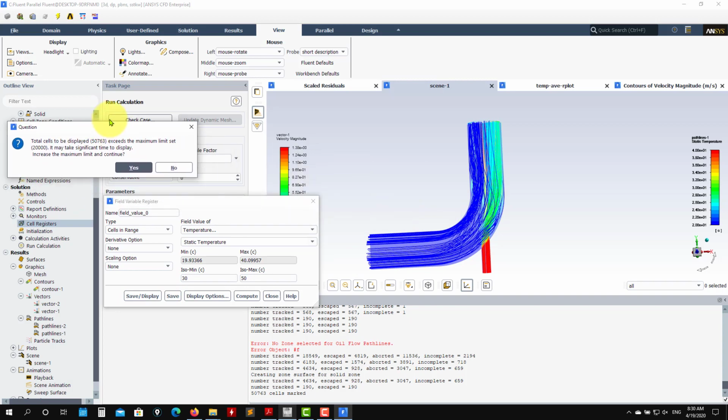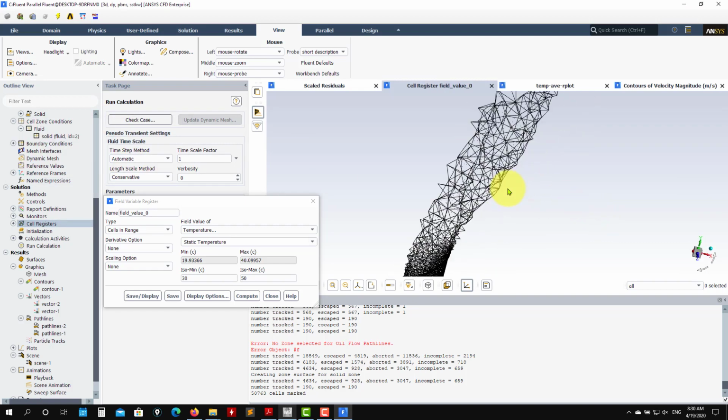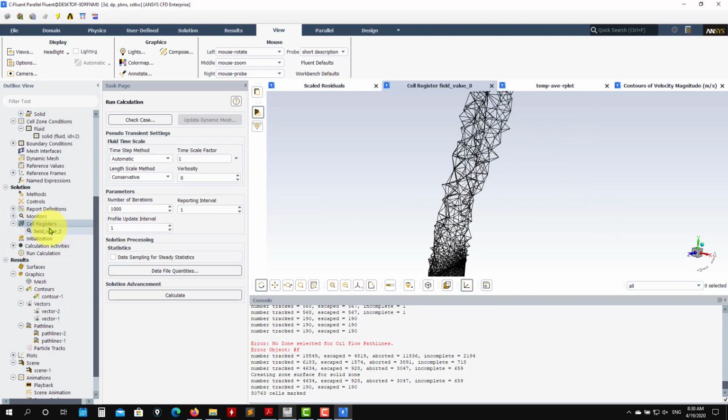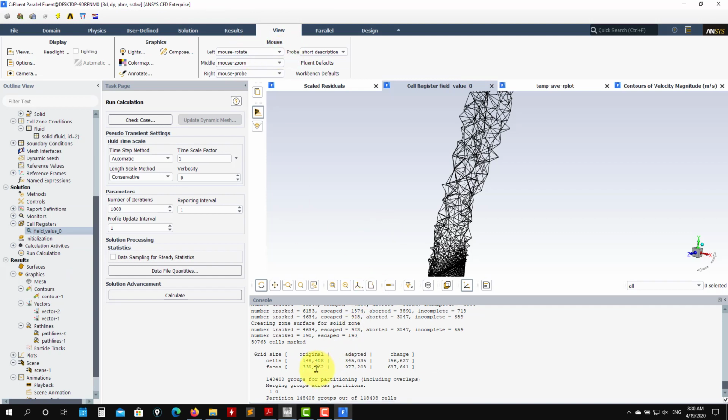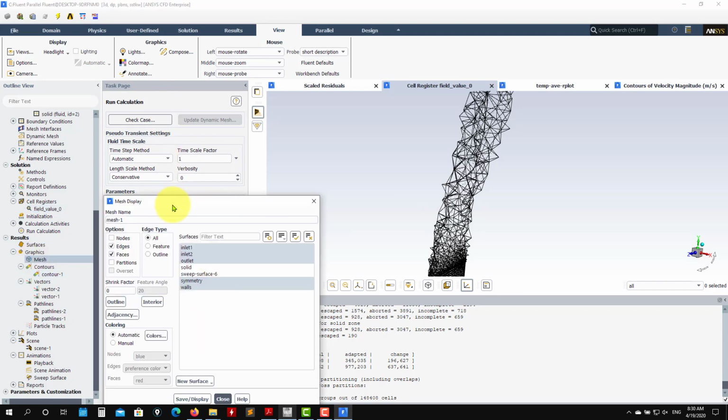It's giving you this warning that it's not showing you all the cells just to make it fast, and you see that you are adding that there. Okay, I close. You have your field there, and then you right click and you refine. It will do the refine. Remember, previously I accessed that there, and now I right click and you have it. So see here that you already have the information, and let's visualize the mesh, and you will see that now we have tetra. Okay, and you will see that also with tetra it works, but it uses a different algorithm.